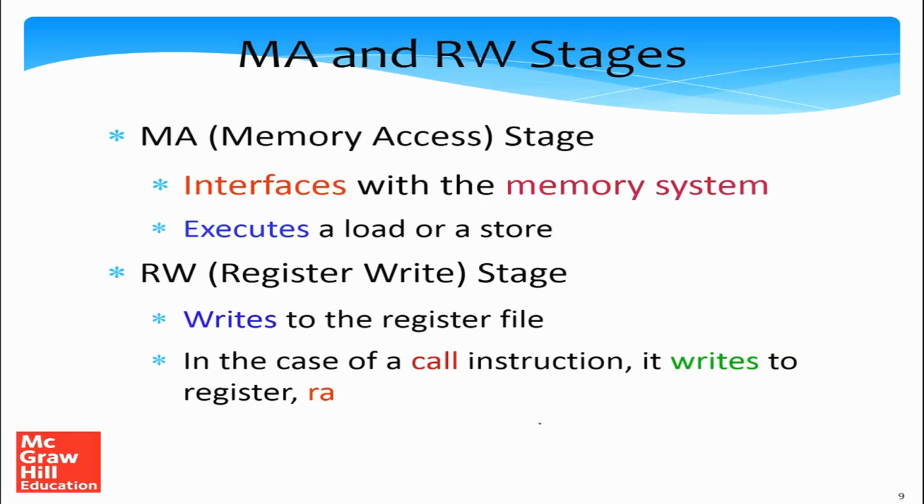Subsequently, we have the memory access stage, which interfaces with the memory system and executes a load or a store. And we also have the RW stage at the end, the fifth stage, which writes to the register file. And in the case of a call instruction, recall that the address of the next instruction was saved in the return address register, RA.